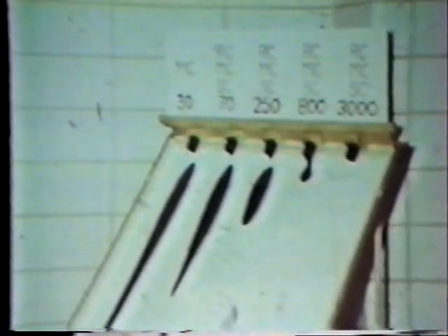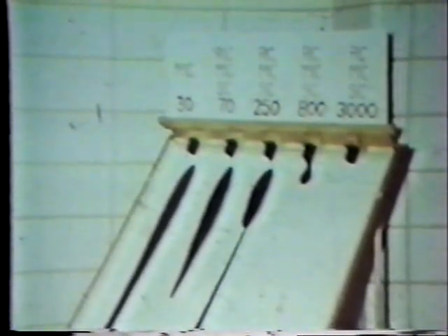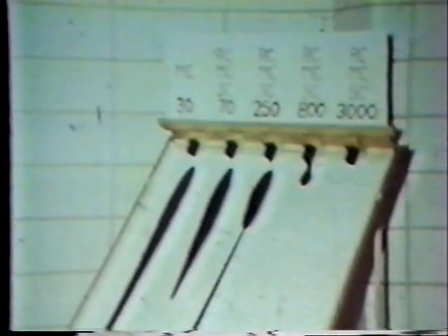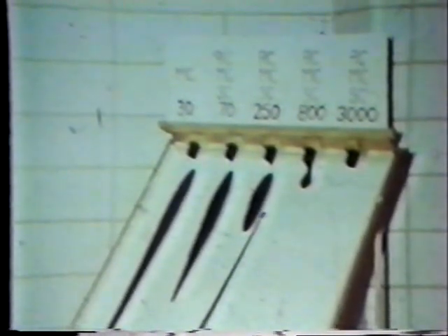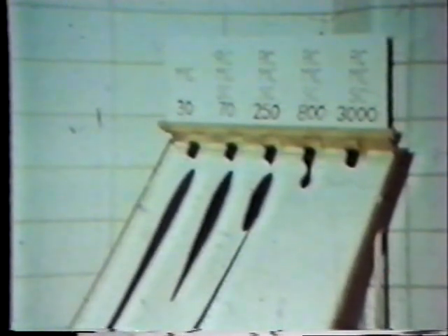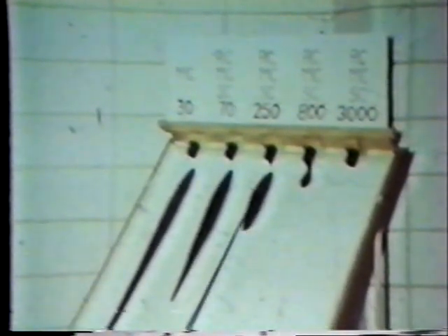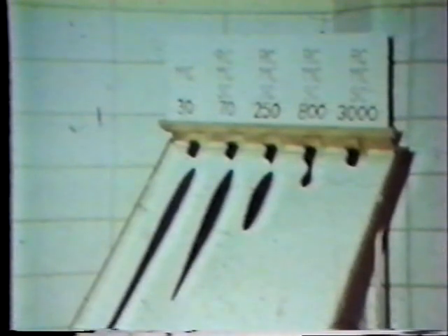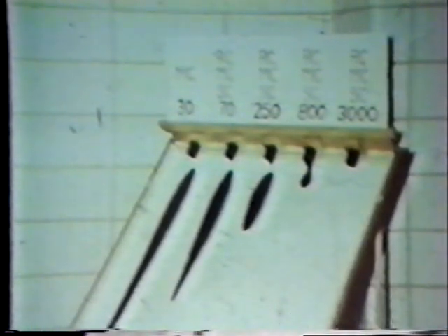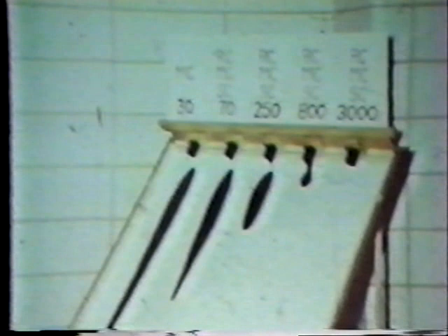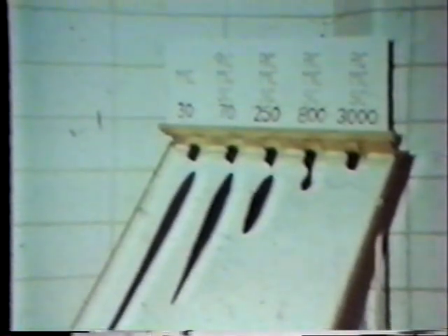On the other hand, if you're making some cold stockpile patch mix for pothole repair, you want something with a little bit more sturdiness to it, a little more asphalt in it, but yet alive enough so that the stockpile stays alive all winter long so you can use it. So you use MC250. If you use MC3000, you wouldn't be able to touch the pile. It just wouldn't move, wouldn't be workable.